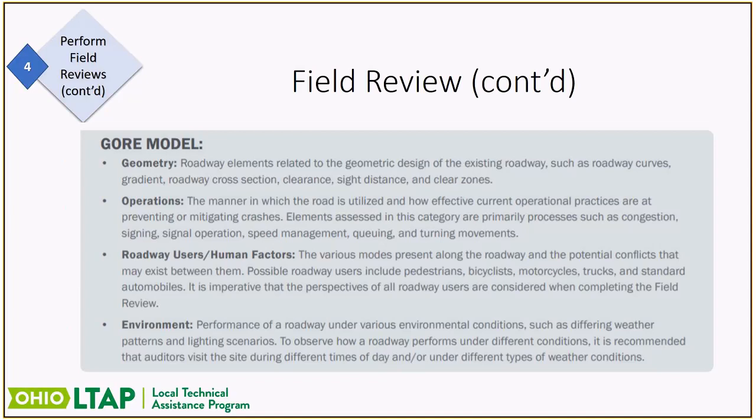We try to encourage you, when you're doing your road safety audit, to look at the road at the time that you can determine from the data where it's having the most issues, the most crashes. But if you can't, for whatever reason, get out during that time, you can always go out and film it, hopefully at that time. I've gone out at different times of the day or night to catch video footage of a roadway to be able to share with a team when they went out to look at it at a different time of day. But it's good if you can get out at the actual peak time.